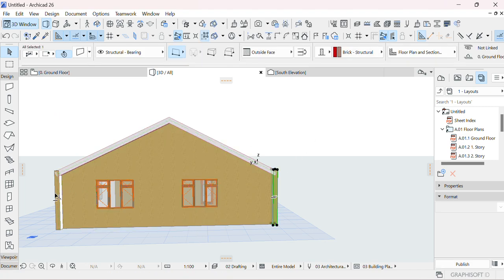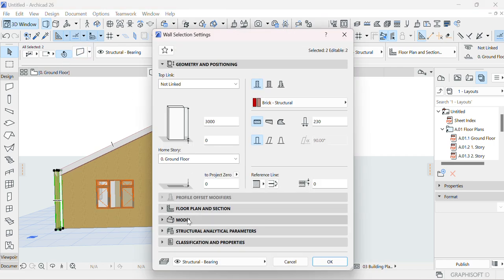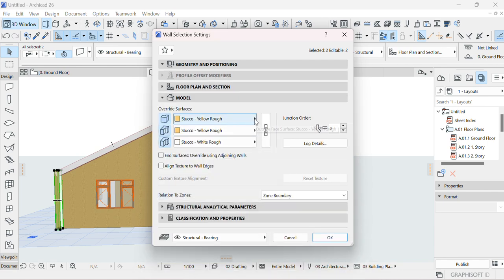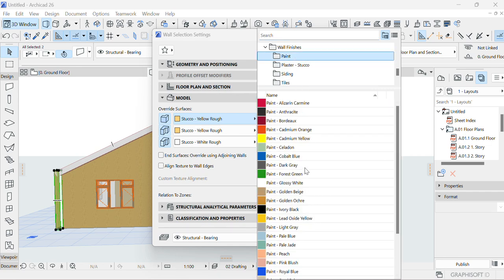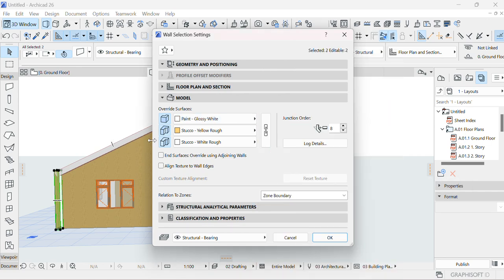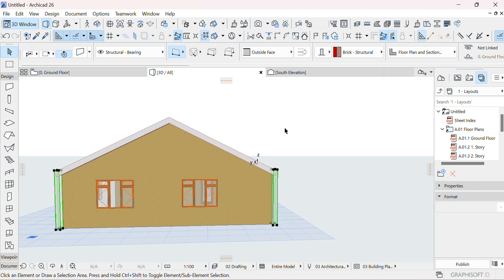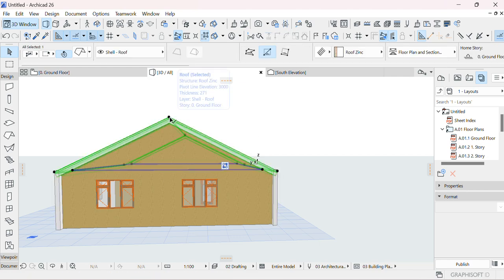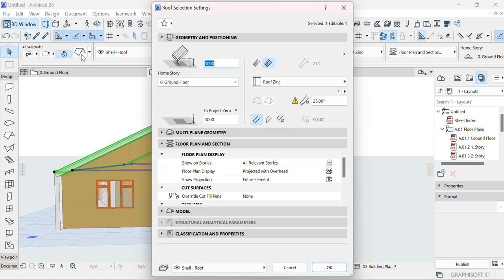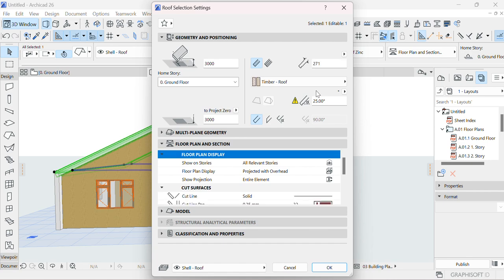Then these ones I can make them look like that. So I can change the material to gloss white, which is the same as that. Then I can just make everything white here by linking that. See? But it's not coming out. Let me just increase the thickness of that so that it comes out more robust. Probably because these are pre-made, I can use the plain one, which I can adjust to whatever height I want. Maybe I put it to 500. Then say okay.